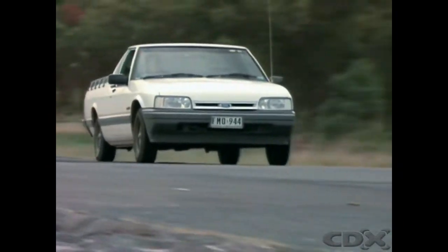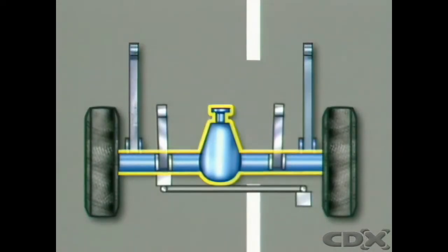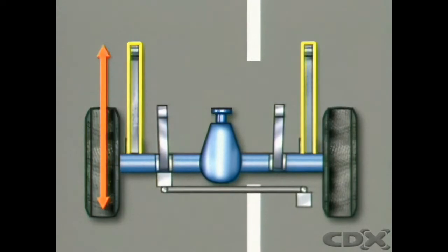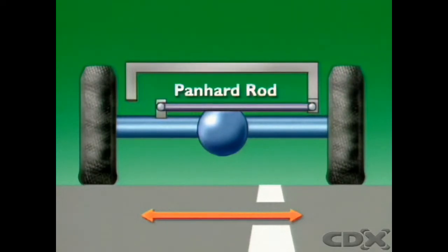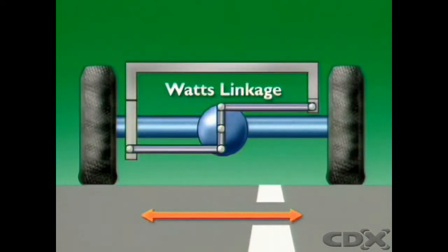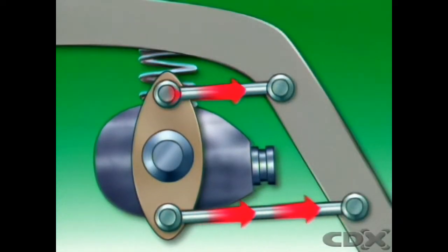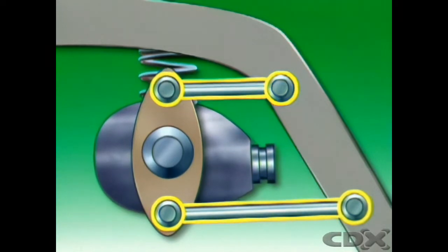Leaf springs perform these functions well, but the transfer of forces interferes with the suspension function and ride quality is compromised. On an axle of this type, the use of coil springs allows the spring to carry out the function of suspension only. The axle housing is usually located longitudinally by upper and lower control arms, and laterally either by the angle of the control arms or by a separate panhard rod or Watts linkage. The control arms have flexible bushes at each connecting point to allow for suspension movement. The driving thrust and braking torque are transferred through the control arms and bushes to the frame.